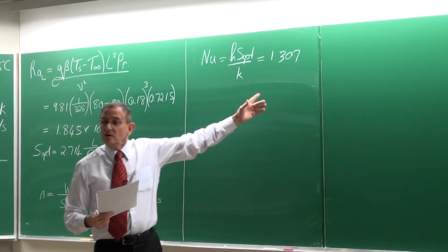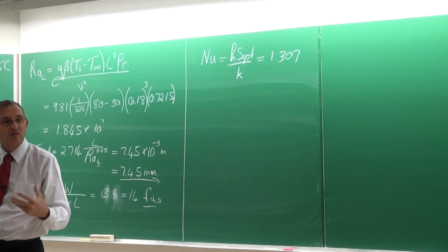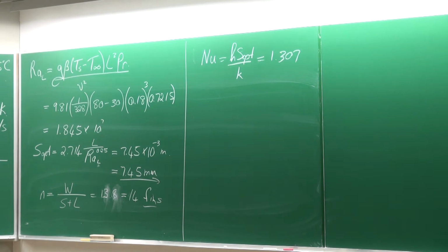It is low, but that is typically what happens with natural convection. It has relatively low values of heat transfer coefficients and Nusselt numbers. That is why with many electronic types of applications, they need to use a fan, and these days they are also investigating technologies where they've got so-called microchannels, and in the microchannels there would be a fluid that is actually being boiled and is actually transferring the heat from the material to the fluid.